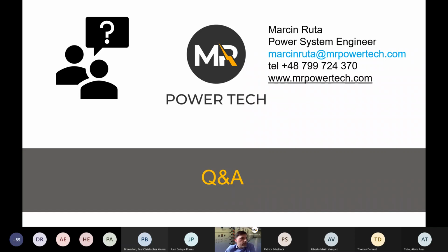Some software allows you to use the comprehensive short circuit method. Do you use this method for arc flash evaluation, or do you stick with IEC 60909? Is it good practice to use the comprehensive method for the arc flash study and IEC for the recommended equipment evaluation?